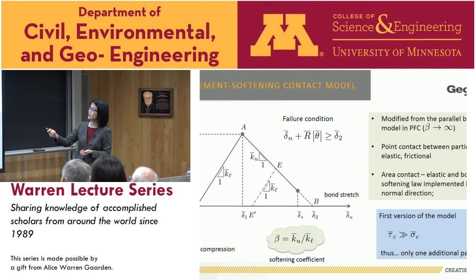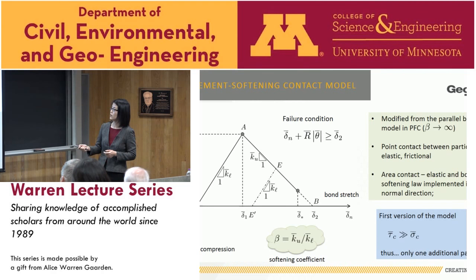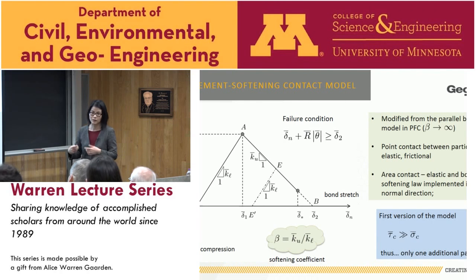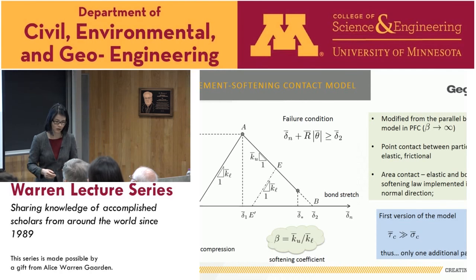And the only new parameter we added to it is what we call the softening coefficient. That's the unloading stiffness over the loading stiffness. So the unloading stiffness and this loading stiffness. This is the only new parameter we added to the parallel bond contact model that's in PFC.